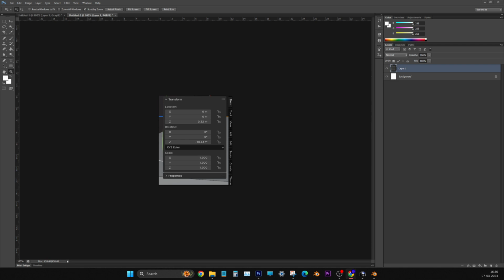So at that time if you just put the value 1 in the x axis or y axis or z axis in relative offset, it will duplicate in a linear form, a straight form. Linear means straight form. See, either upwards or downwards, it is duplicating. You can see the staircase. You can try it. It will go only upwards.